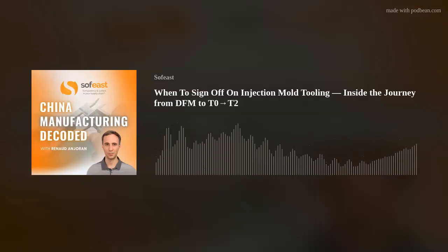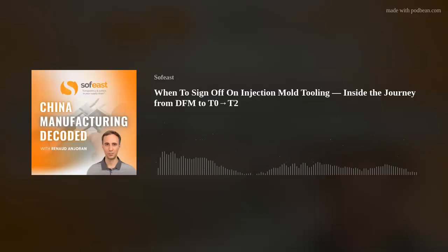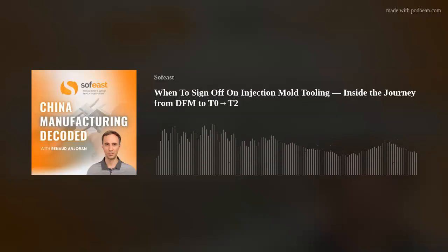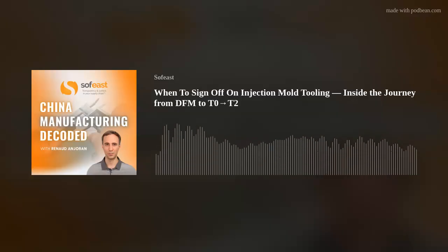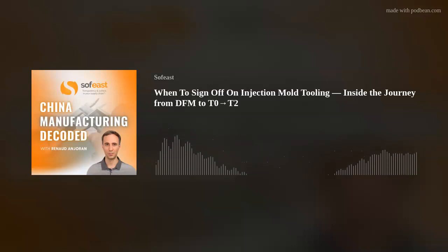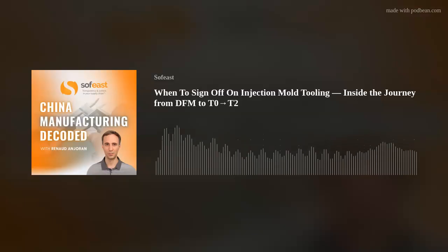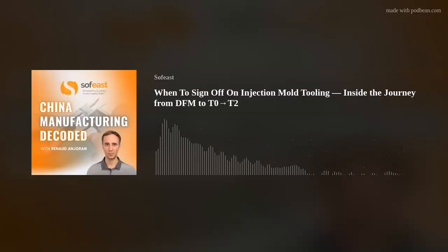So we're actually sparking out a very detailed shape. That's the EDM side. We've also got some wire cutting, grinding, and then we go into polishing, and ultimately we're fitting everything together. Before we do the fitting, we do the surface finishing from a hand polishing point of view. We've got two very skilled people within our plant that do this day in, day out. And absolutely, some of the surface finishes they get, like a mirror finish on some of these things.